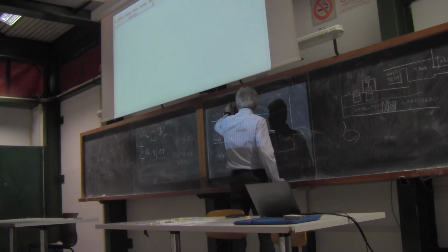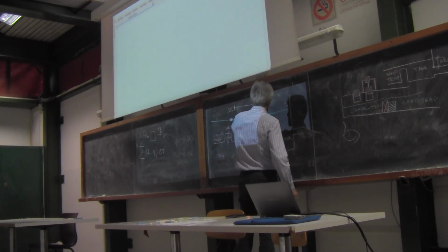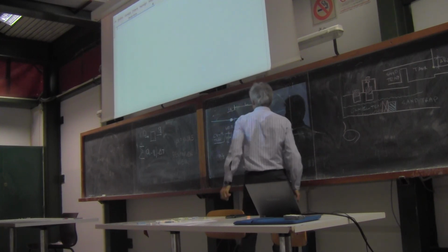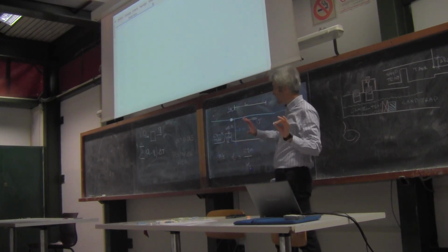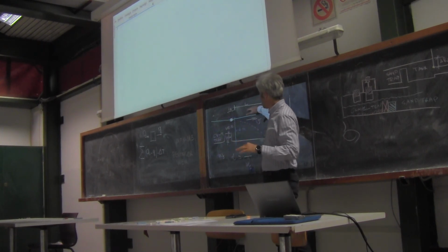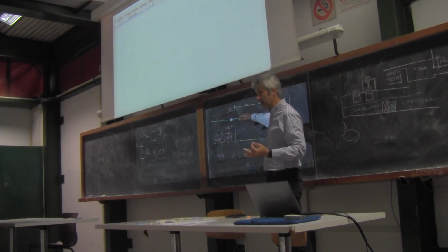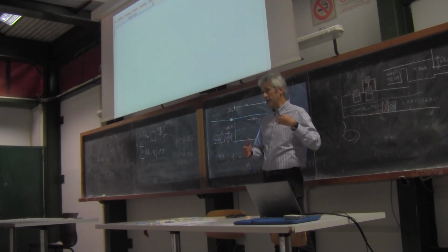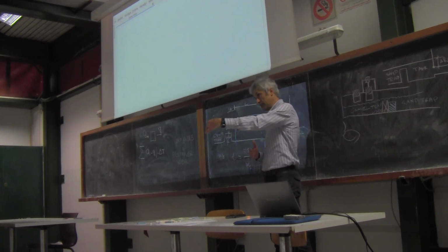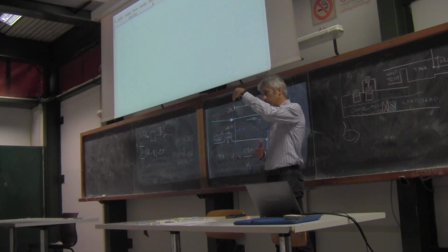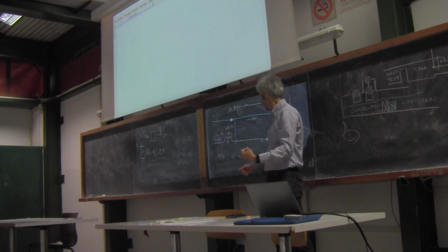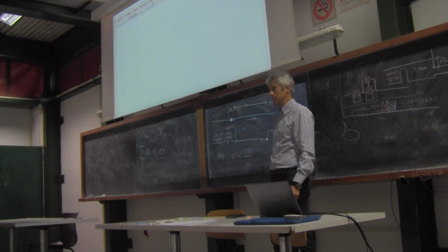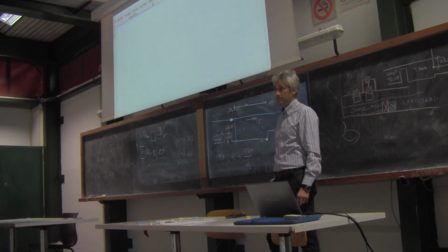Therefore, we have to make sure that the length, let's indicate it with L, not sure whether I used this symbol in the slides, but it doesn't matter, we need to design L to give enough time to the particle while it moves forward to also move vertically and reach the bottom of the sand trap.